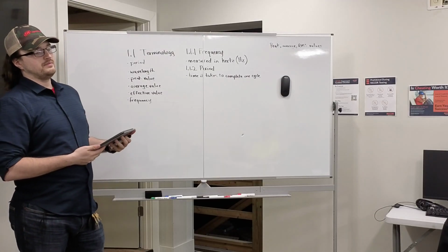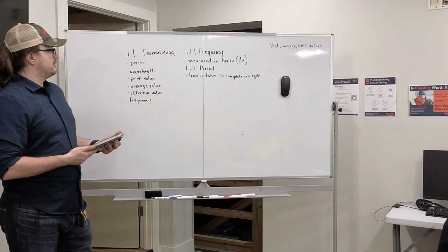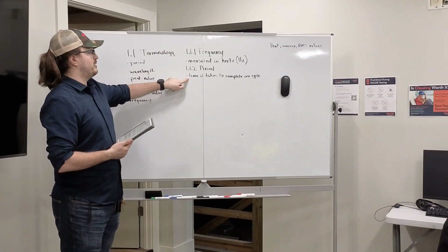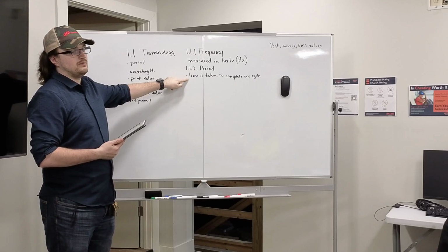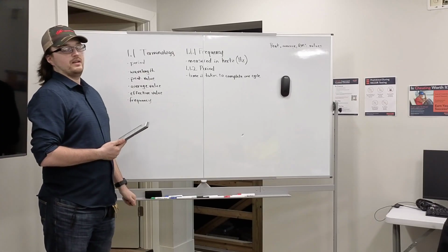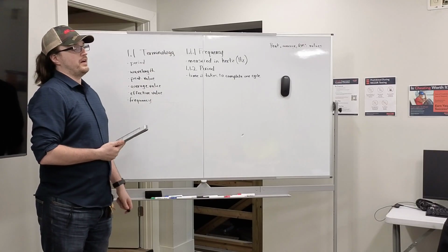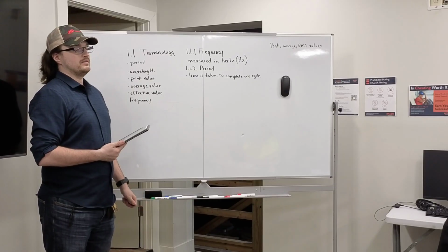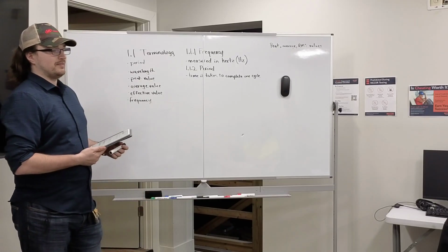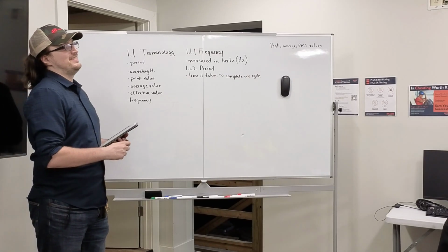There's a formula. It's 1 divided by the frequency. Okay. The period is how long it takes to complete one cycle. What's a cycle? 360 degrees of one. Okay. How many cycles are in that figure? 5. And what is the time frame of those 5 cycles? 5 tenths. So what is the period of one of those? 0.1. Yeah, all right. You said that after you yelled like 10 other things first. I said 0.1 first. No, you didn't.